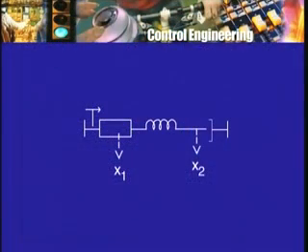and depending on whether this is less than or greater than the natural length, the free length of the spring will be in compression or in tension, and therefore will produce, or it's being affected by a force of compression or a force of tension. Similarly, the dashpot, one end of it is fixed, the other end of it is connected to the spring, so the plunger of the dashpot moves, therefore one can talk about its velocity, and so on.